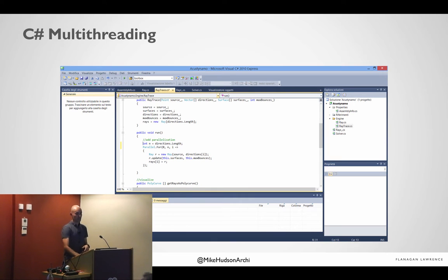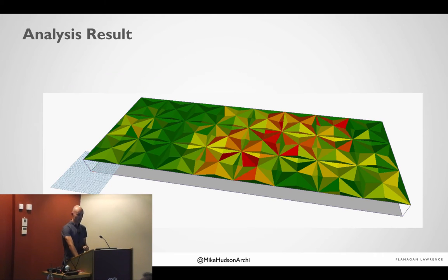What we realised, however, and as mentioned earlier, is that you can start to use C# inside Dynamo, so you can actually improve the processing time for multiple complex calculations. Essentially, this is something we just found on the internet. It's a multi-threading algorithm. You can build that inside a node, inside anything that you're doing for an optimization, and you can just run your processes considerably faster. It will use all of the cores on your computer rather than just the single core that Dynamo will traditionally use.